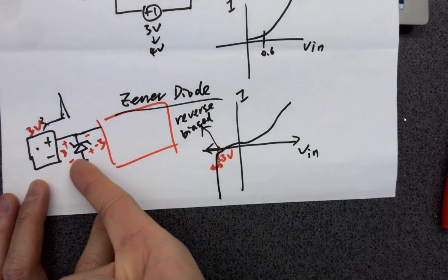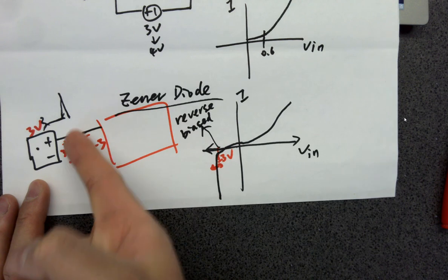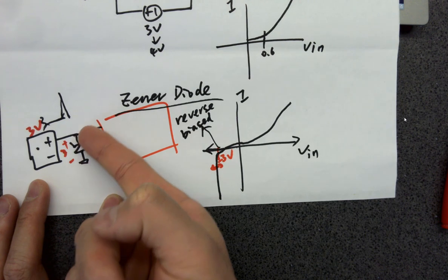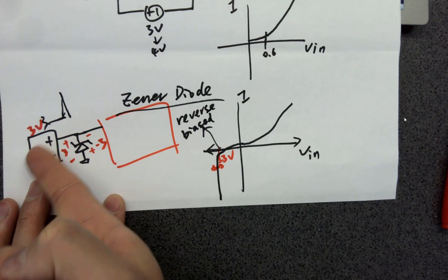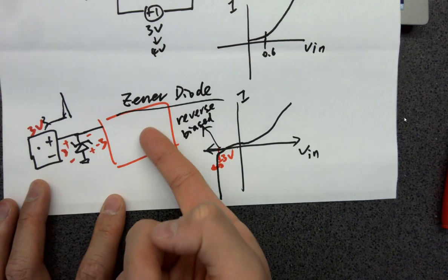But now I'm reverse biasing these guys. That is why eventually I'm getting a plus minus 3 volts at this point. So eventually, it's helping this voltage regulator to avoid any surges and to protect the circuits after that.